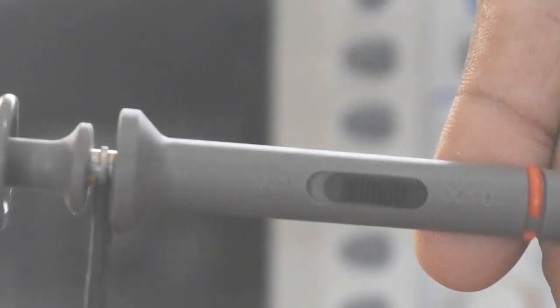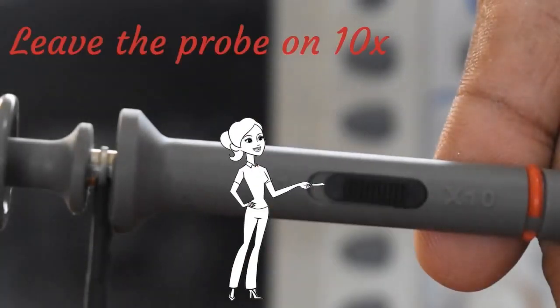Now, I recommend leaving the probe on 10X, as that is the best compromise between signal attenuation and having the probe affect the circuit you are trying to measure. However, we need to inform the oscilloscope that we are using a 10X probe and we need to tune the compensation capacitor in the probe. You will see the use of the compensation capacitor later. Stay tuned.